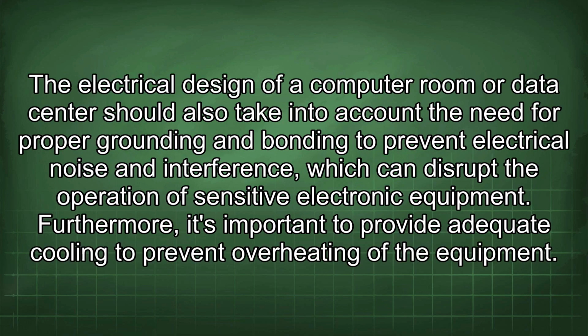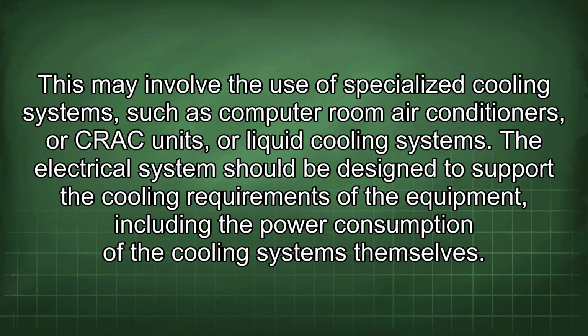The electrical design of a computer room or data center should also take into account the need for proper grounding and bonding to prevent electrical noise and interference, which can disrupt the operation of sensitive electronic equipment. Furthermore, it's important to provide adequate cooling to prevent overheating of the equipment. This may involve the use of specialized cooling systems such as computer room air conditioners, or CRAC units, or liquid cooling systems. The electrical system should be designed to support the cooling requirements of the equipment, including the power consumption of the cooling systems themselves.